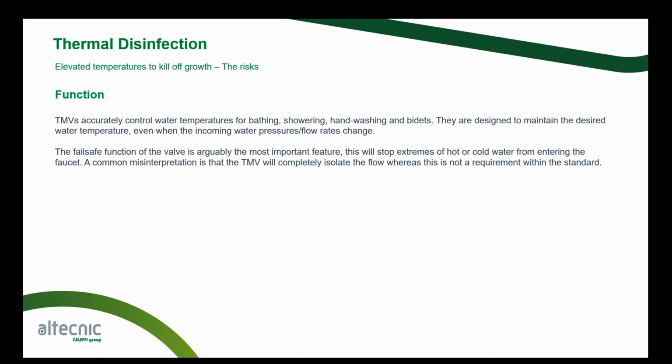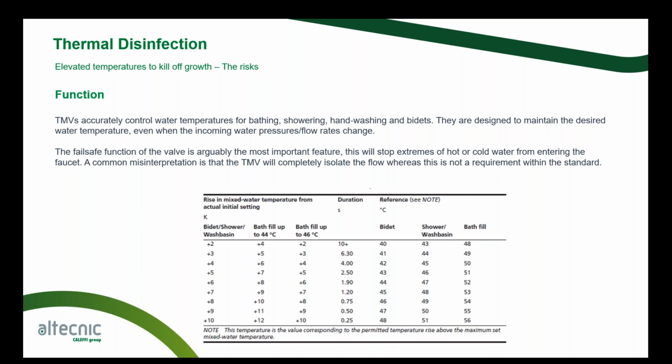Now the fail-safe function of the valve is arguably the most important feature. This will stop extremes of hot or cold water entering the faucet. The common misconception is that TMVs will completely isolate the flow, whereas it's not always a requirement of the standard. So if anybody does work in healthcare, when they're looking at mixing valves and carrying out maintenance on these valves, look at the fail-safe feature.